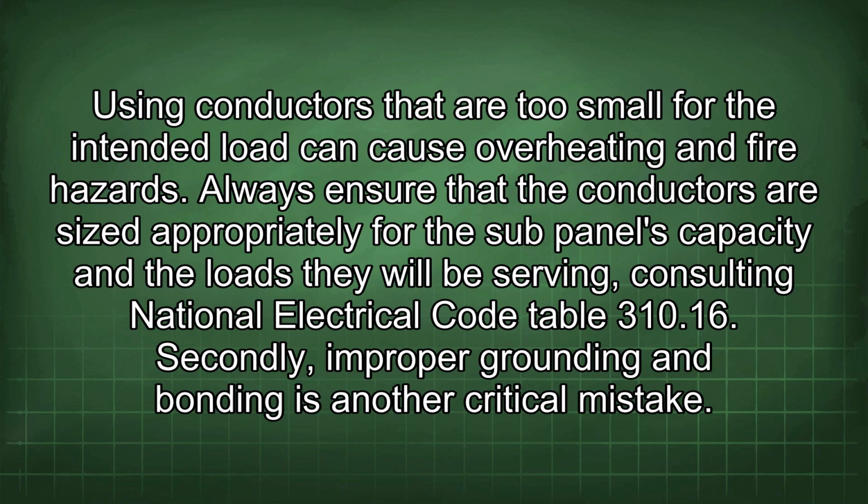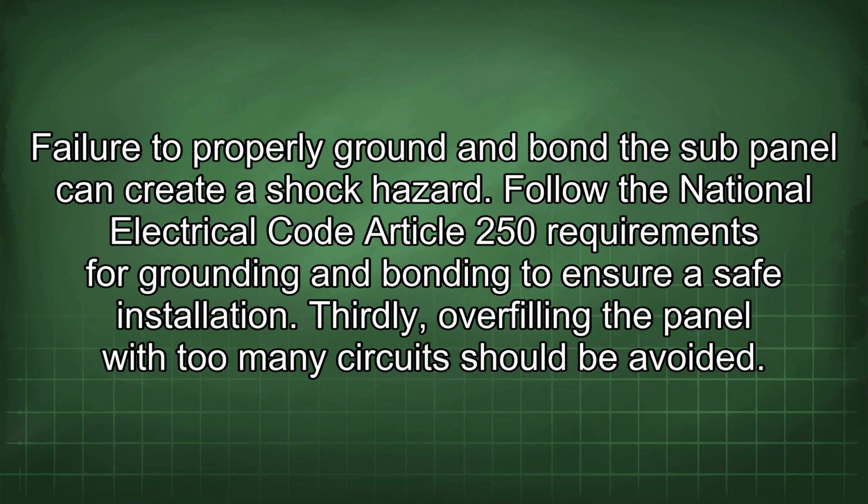Secondly, improper grounding and bonding is another critical mistake. Failure to properly ground and bond the sub-panel can create a shock hazard. Follow the National Electrical Code Article 250 requirements for grounding and bonding to ensure safe installation.